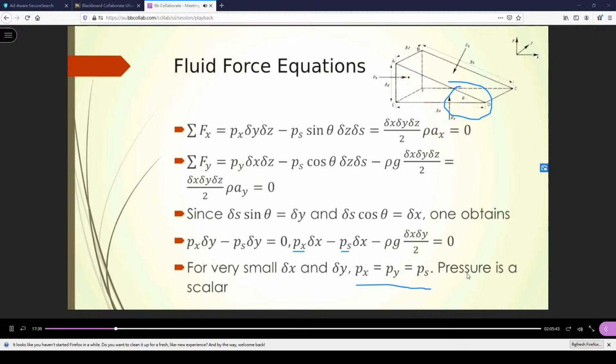So now you will understand that pressure inside a fluid does not carry a direction, right? No matter which direction you consider, the pressure is the same. Therefore, unlike velocity, pressure is a scalar. So pressure has no direction. The force has, right? Because the area acted upon by the force has a normal. Sorry, a force is a vector and pressure is a scalar.